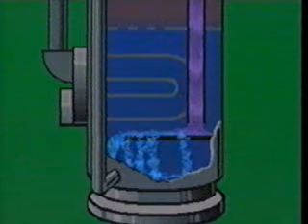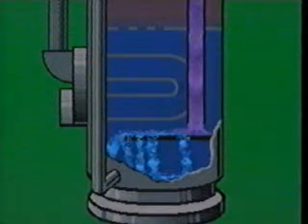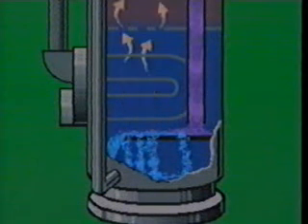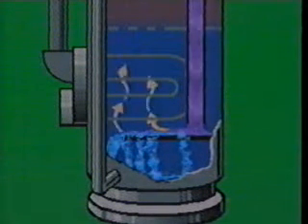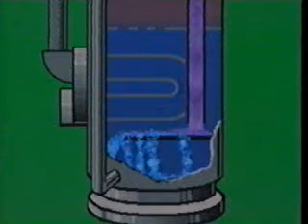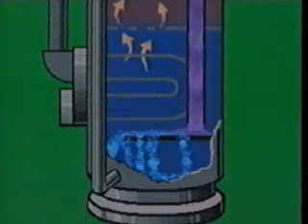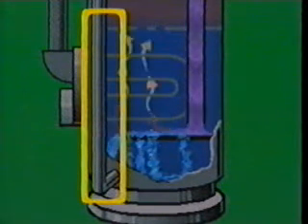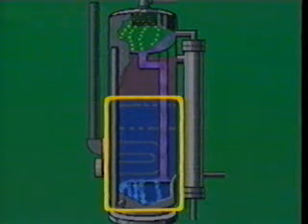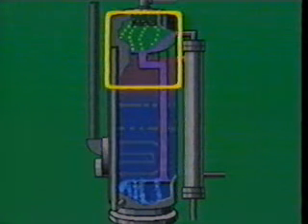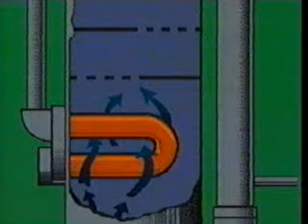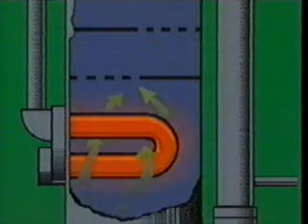After leaving the gas separation section through the downcomer, the emulsion enters the free water knockout section. Now here, most free water quickly settles out, and the remaining lighter liquids move upward through the water, which acts as a heated wash. As the treating process continues, the siphon system removes excess free water. The water section of vertical heater treaters occupies about 60% of the fluid column, leaving 40% for the oil and gas section.